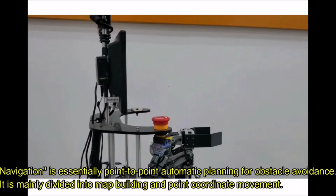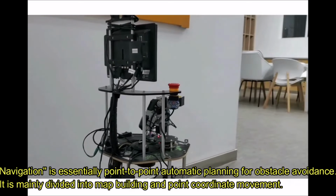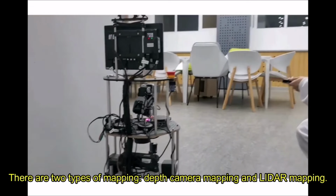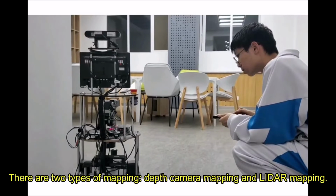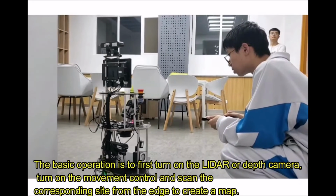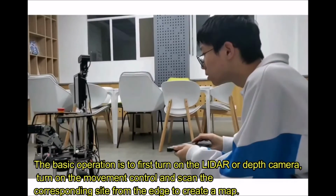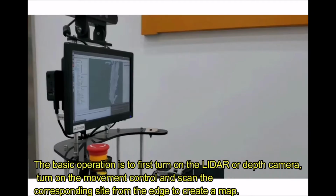Navigation is essentially point-to-point automatic planning with obstacle avoidance. It's mainly divided into map building and point navigation. There are two types of mapping: depth camera mapping and lidar mapping. The basic operation is first to turn on the lidar or depth camera. Turn on the movement control and scan the surroundings from the edge to create the map.